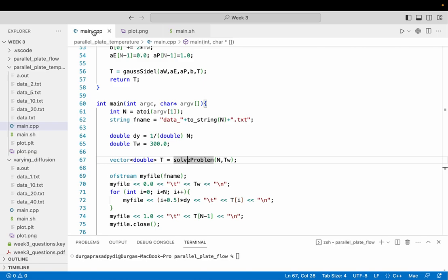We're out of time, but I'll try to make it faster. Forget there's no movement of fluid. It's constant heat. You take a line, then it will be pure conduction. Like whatever we have discussed today, this pure conduction equation, ∂²T/∂y² equal to zero. So if, say, it's 300 degrees on the top and 0 degrees at the bottom, eventually it has to be a slanted line with that slope, 300.